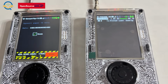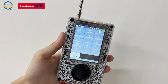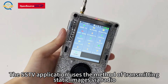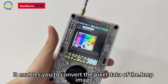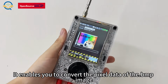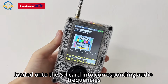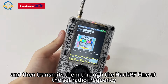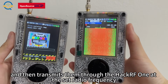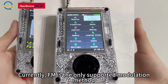SSTV. The SSTV application uses the method of transmitting static images via radio. It enables you to convert the pixel data of the .bmp image loaded onto the SD card into corresponding audio frequencies, and then transmits them through the HackRF at the set radio frequency. Currently, FM is the only supported modulation method.